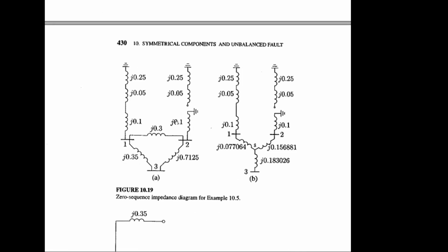Be careful about zero sequence network diagram configuration, especially for transformer part. Okay, when we want to put the equivalent information for all the generator transformer, here you can have transformer 1, transformer 2. Okay. Regarding transformer 2, here you have some open terminal because of delta in the upper part. Lower part is the Y and upper part is delta. And I have already shown the equivalent circuit for transformer internal configuration for Y delta.